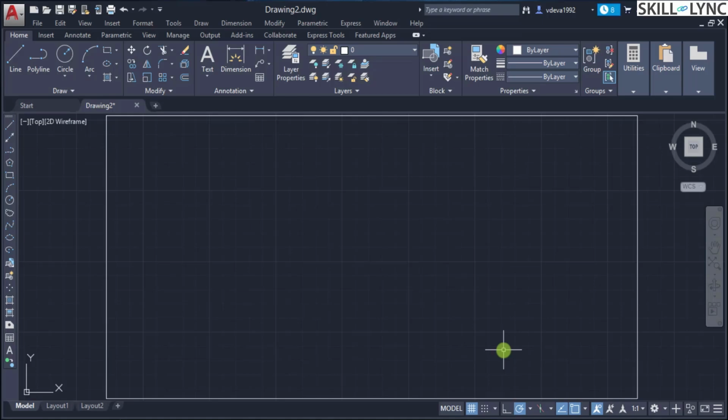So next we have the zoom to previous view option. We can roll back up to 10 different zoom options that we have invoked earlier. This is different from an undo command. Undo typically rolls back the action that you have done. It might be a drawing action or a deleting action also, but this zoom to previous restores only the zooming actions or viewing actions.